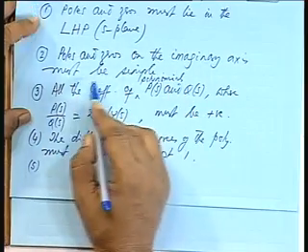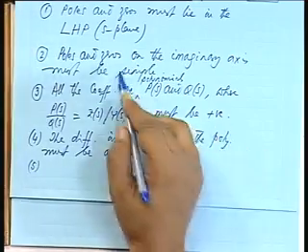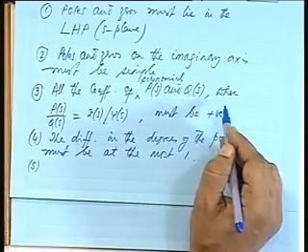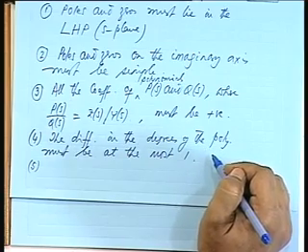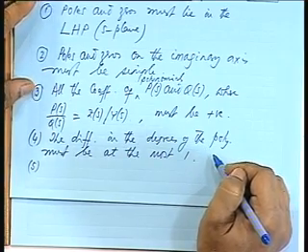Poles and zeros must be simple on the imaginary axis, the coefficients must be positive, and the difference in the degrees of the polynomials must be restricted to 1.